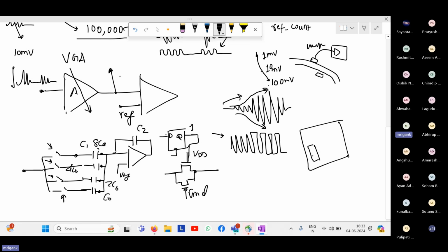So these are the flip flops. So 1, 2, 3, 4. This is a 4 flip flop register, 4-bit register. Now from one of the pins of the chip, you will insert that data 1, 0, 1, 0. In 4 clock cycles, you can enter the data in these flip flops. Now let me draw it more clearly.